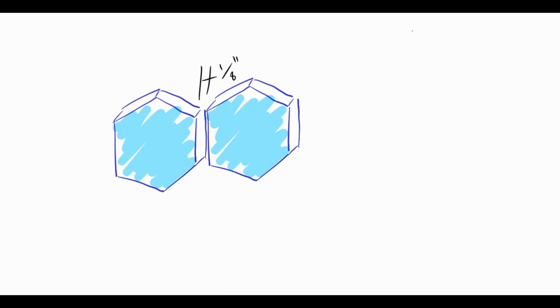I quickly realized this was overly optimistic, though, because the gap between the tiles, which is supposed to be 1/8 of an inch, is actually a little under that, and there's just not sufficient room for all that. A standard PCB thickness is about 1/16 of an inch, so that only leaves about 1/16 of an inch left for components. I also had some scope creep, which meant that I needed to put more components on the circuit boards, meaning I needed more board space, so even if it would have fit in the crack, I don't think I could have put enough in that much area.